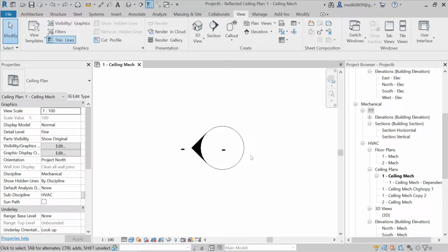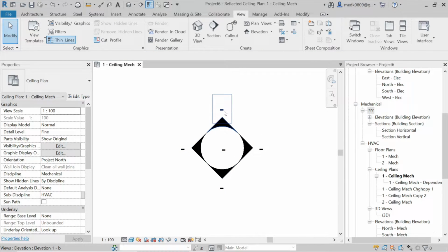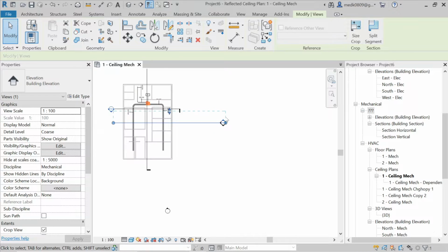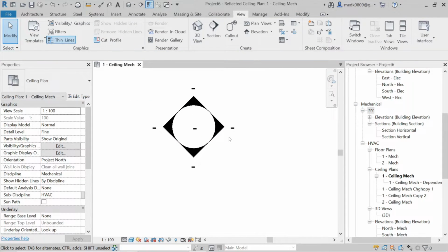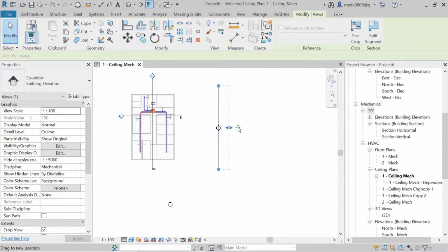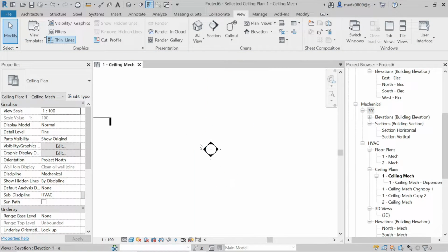If you want to apply more views to this elevation, just click on this minus sign in this circle, and you can apply more views to different directions. Okay, as you can see I have checked all the directions. So with the help of this one elevation you can see the 4 sides. See, if I click on this arrow, you can see the view range of this particular arrow. Or if you select this arrow, you can specify the elevation of this particular arrow. So in such a manner you can create elevations in Revit.